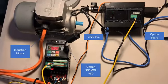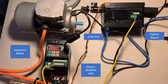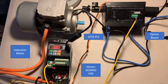As you can see, the MX2 VSD is fully controlled by the CP2E PLC via the Modbus RTU network. Use Modbus RTU to control the speed setup. Use Modbus RTU to control the VSD start and stop. In conclusion, CP2E's simple Modbus RTU master function is definitely a simple and economical solution for machine builders, OEM customers, water industry pump control, etc.